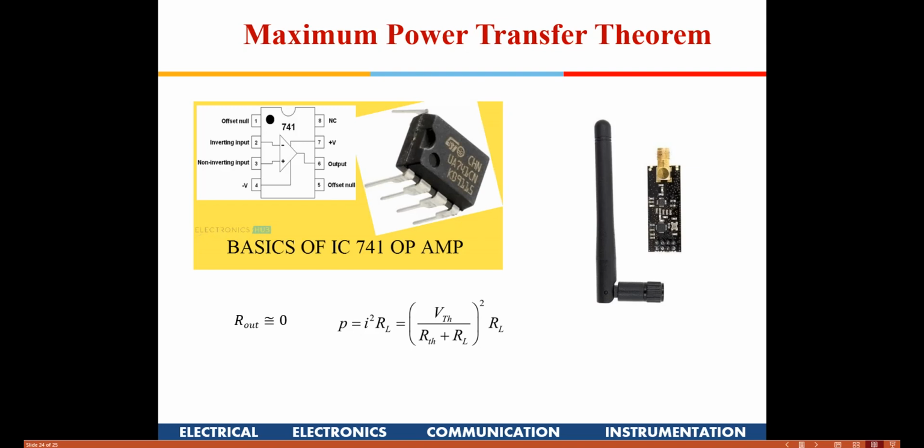So you have to be careful. It's all very critical. In the receiver section, if you don't match it properly, you might not get the entire energy. Whereas in the transmitting section, if you don't do the impedance matching properly, the energy which you want to transmit will not get transmitted, and instead will get dissipated as heat in the circuit. So impedance matching is always a very, very critical issue.